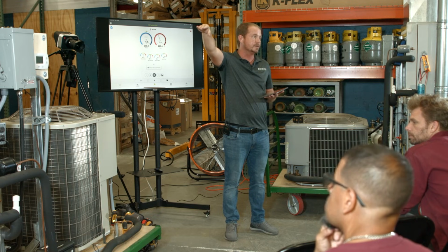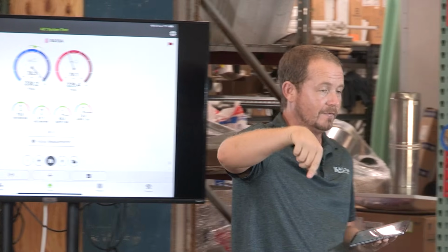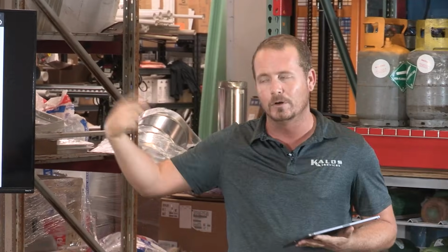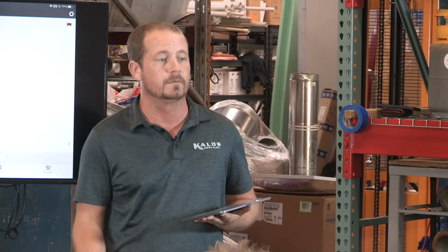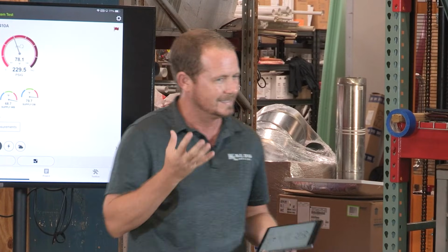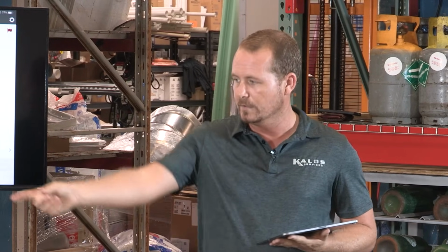Now, is it that much? I don't know, but we would know if we turn the fan on, right? If we run with the fan in the on position, then we would have a better sense. Be careful because the motor does add a little heat as well, so it's not perfect. The best way would be to take them both and put them right in the same airstream. If you're in doubt, run some air over them and see. Even just having them in still air like this, they're not going to be as accurate. These sensors are designed to have air moving over them. So putting them both in the return right next to each other and just checking is going to be a good practice, and we're going to do that.